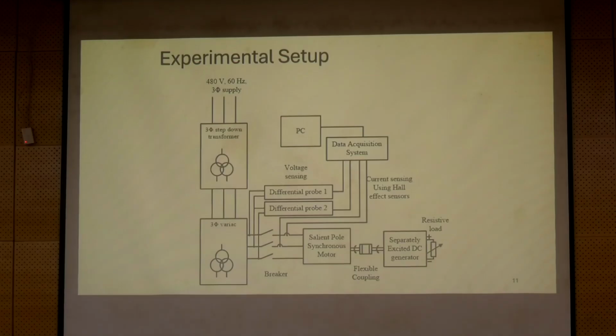In some settings, they are battery operated. So if the battery is low or drained out, data acquisition might not be proper. So we might not even notice that the battery is drained. There might be an indicator, but you might not have noticed it, and you would have collected data and you will see that there is a zero line or just a straight line. So what I'm trying to say is you need to really inspect the raw data as you collect, and only then can you conclude whether this is good enough or not.